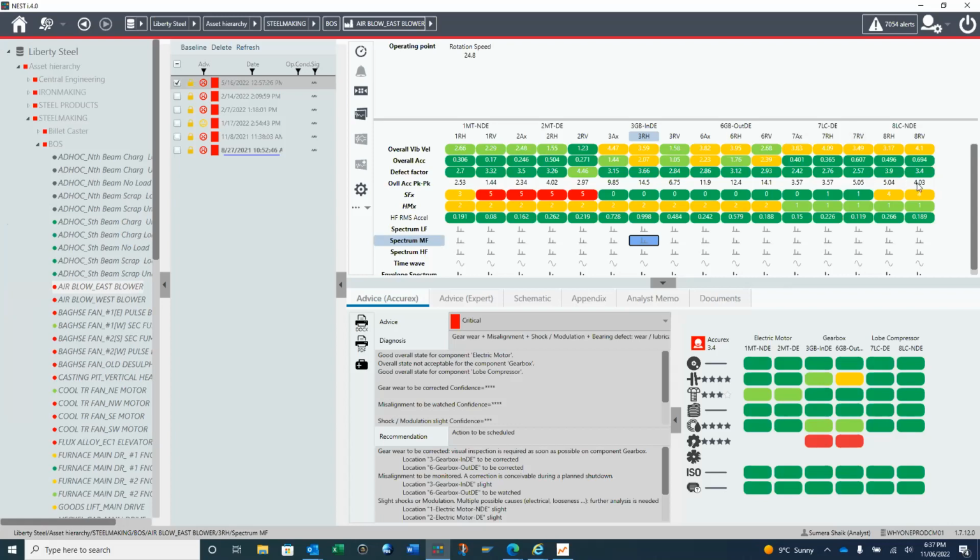But sir, if you see the time waveform, you can see it is very high, like 9.85, 14.5, 6.7. Is that okay to have? Based on my experience, it's still okay. We had a gearbox before that ran to 20 mm per second, 16 mm per second, 17 mm per second. Still okay. And sir, is it okay to have two G's also? See, here it is 2 G's, 2.23 G's.